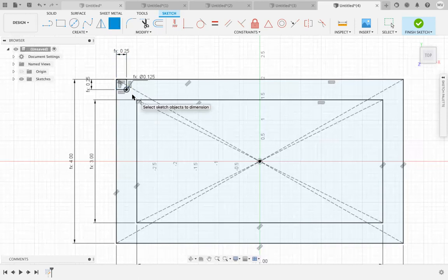Instead of using that square, I'll do it in the top right here. We're going to use just straight up lines. Now, when I click on this edge, do you see the X? It's telling me it's going to be located on that edge, the first point. Click there, and I'm just going to drag down. And how far down do I want it to be? I want it to be half the thickness. So thickness divided by 2. And notice 90 degrees is kind of default because where I have the mouse, I do want it to be 90 degrees. So I can hit enter.